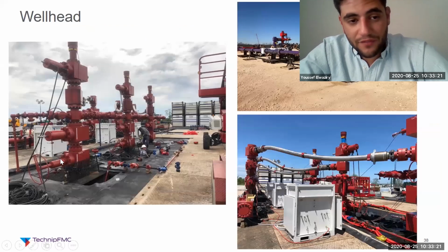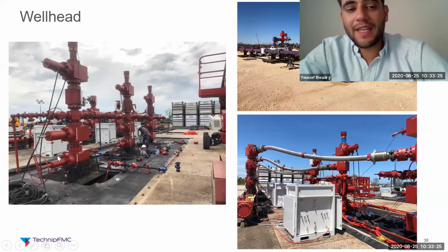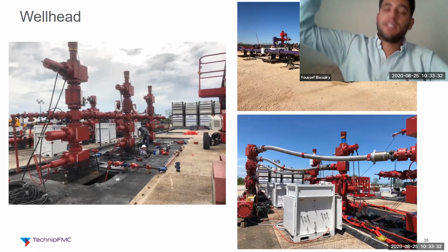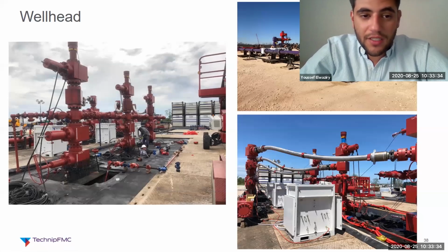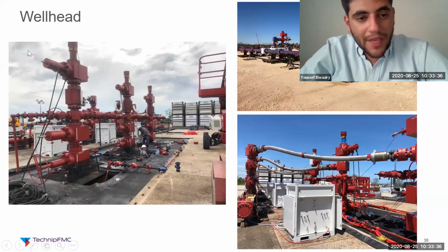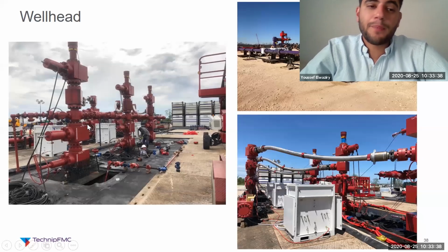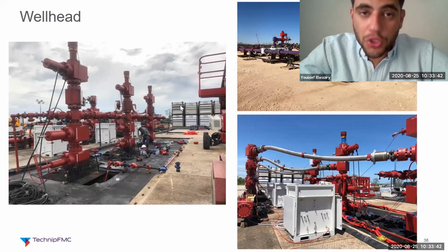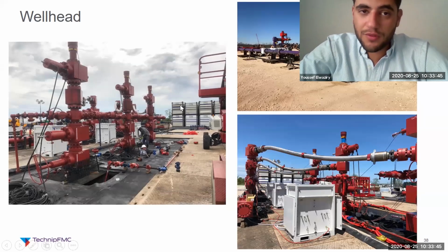And that's why we have several layers. We have a valve here and a valve here, so that in case this valve leaks or is not working correctly, you don't want to have 10,000 psi coming out into the sky uncontrolled. So that's why we have a second valve as a backup. And that's how valves control pressure.